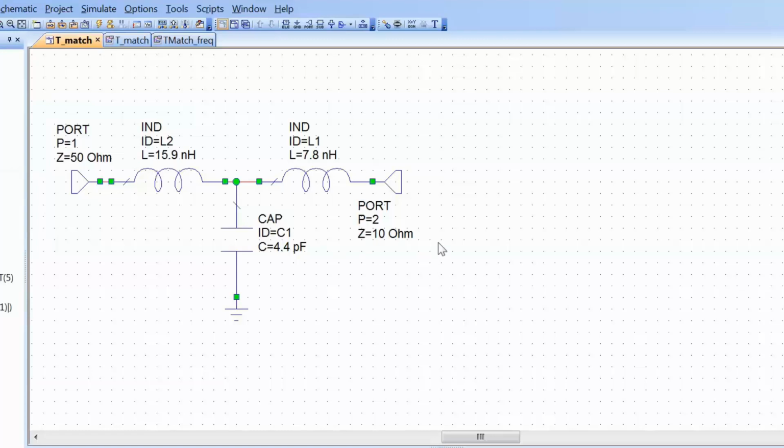So what we can do is devise a T-section matching for an identical network and then compare the two frequency responses. Now the procedure is very, very similar, and in a Blue Peter style I can just come up with one that I made earlier. So let's modify the schematic to have a load impedance of 20 ohms, which is exactly the one that we had for our L-section matching example.